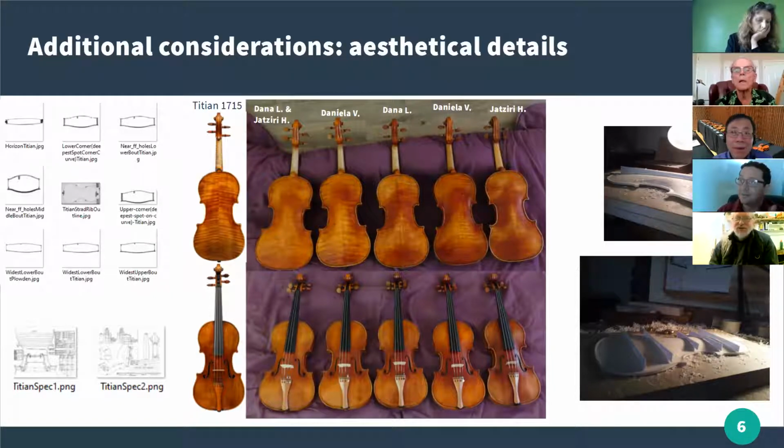Okay. Well, it's certainly a bit of a fool's errand to try and control 100 or more modes in terms of all their properties, all the different parameters of those modes. But I say in some of Colin's work, he's looking at the function of the bass bar and the sound post, and modeling the overall envelope in the high frequency rather than the individual peaks resulting from particular mode shapes. Is that something that you can do in your model?